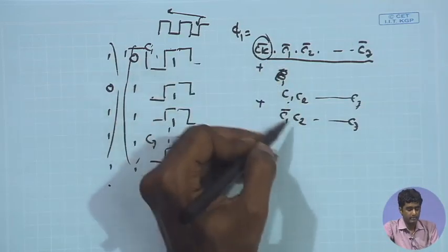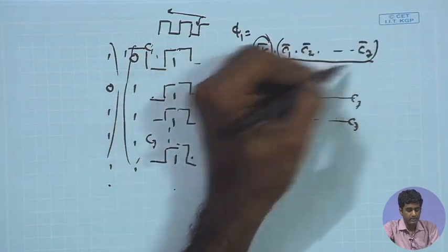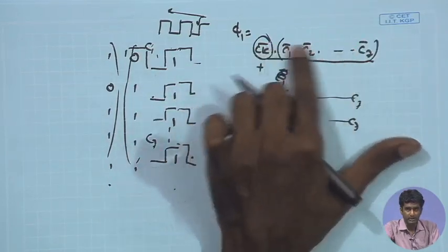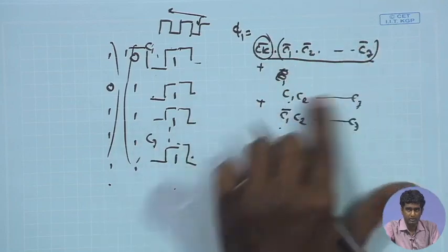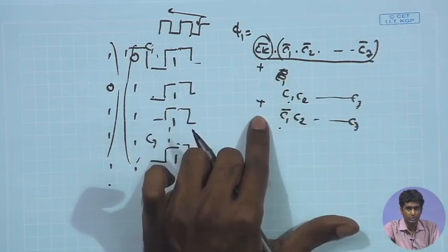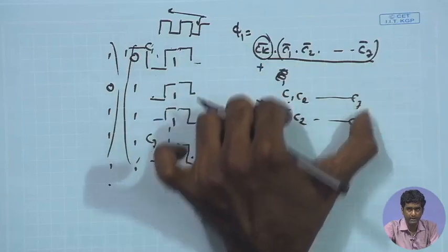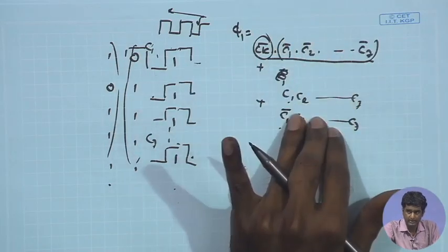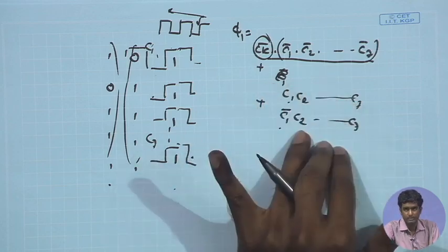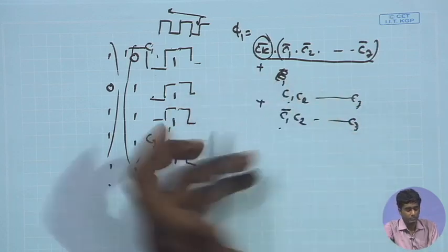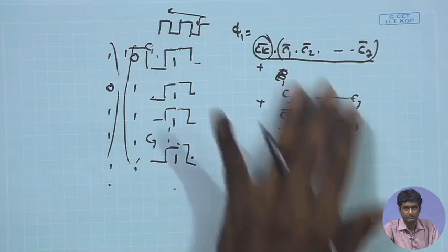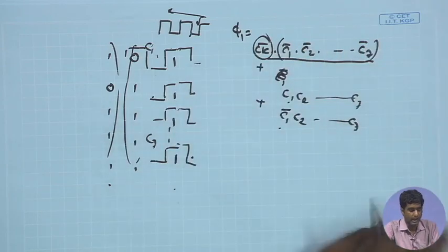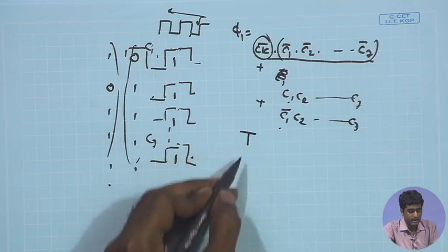So, you have basically the AND gates taking care of these min terms, as they are called, each a combination of AND functions, and then they are ORed together. So, basically a bunch of AND gates followed by OR gates. Now, there is a question regarding the implementation of these AND gates and OR gates at transistor level. How do we implement this? The basic structure we know: if you are trying to implement a NAND gate, from which we can implement an AND gate, we know what the NAND gate looks like.